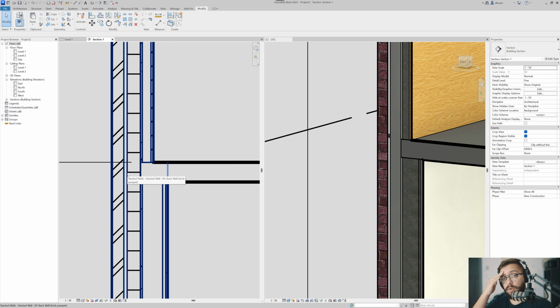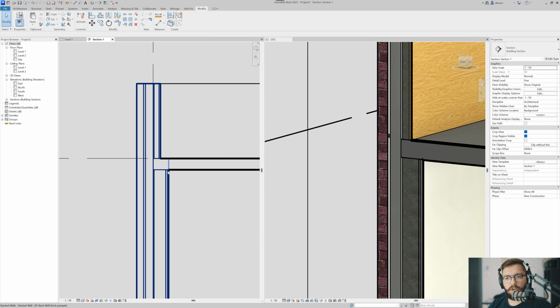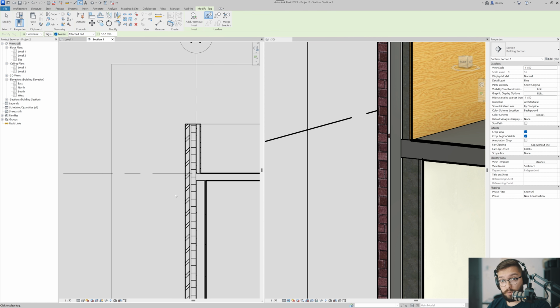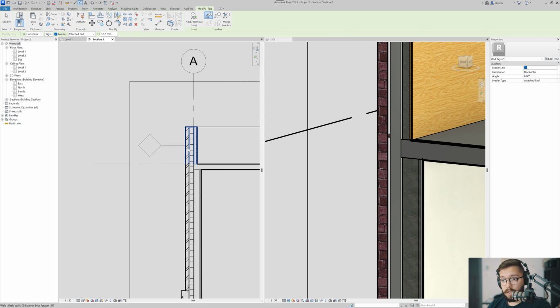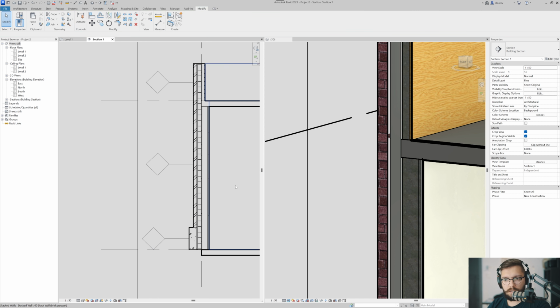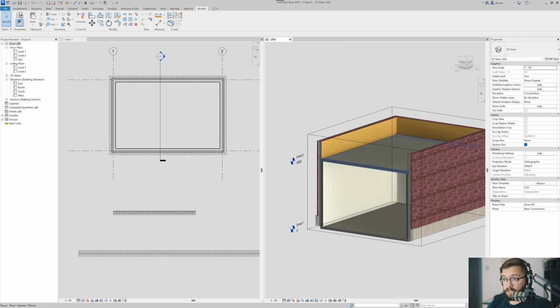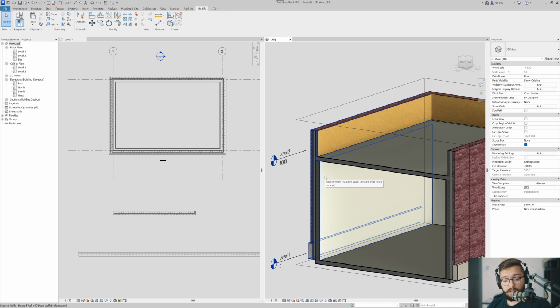So let's say if I'm working on my wall sections, I actually don't need to kind of model anything here. I can just kind of identify everything there is. Very important thing if you're working on a big project, even though you're using a stack wall: when you tag a wall, you see how it only tags the component of the stack wall. So don't worry about it. You're not tagging a stack wall, so your types, Revit would keep on recognizing them. So you're good to go. Topic for another day. Okay, so this is the functionality of a stack wall in a nutshell.